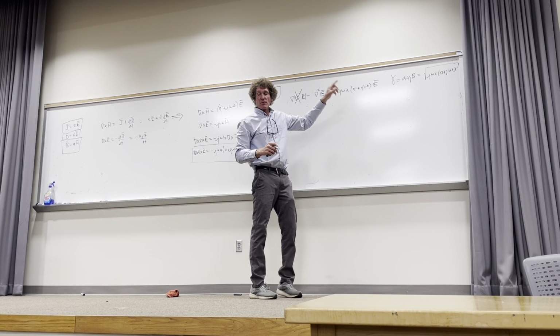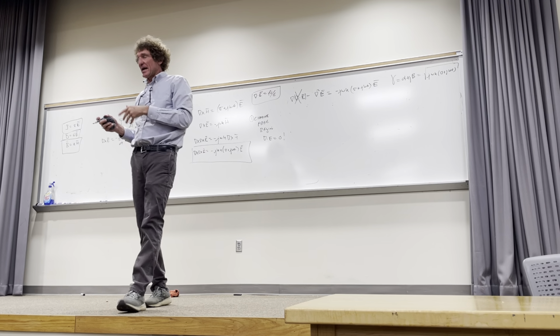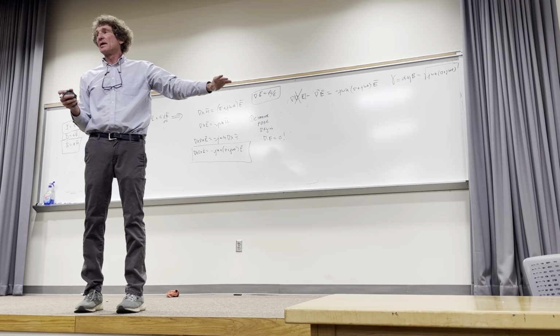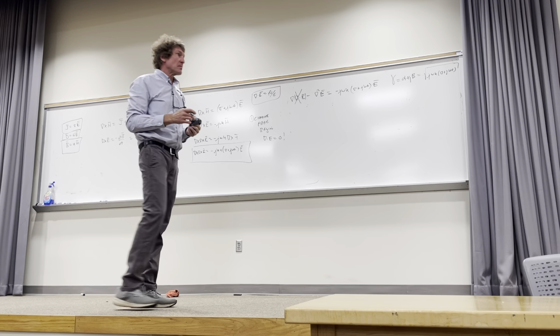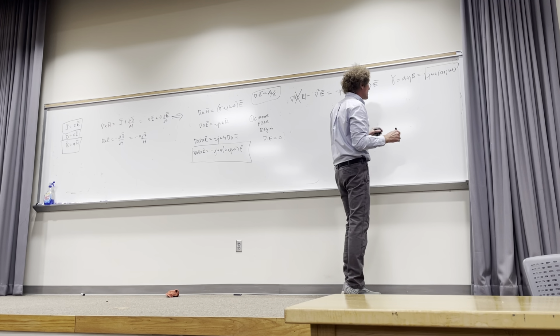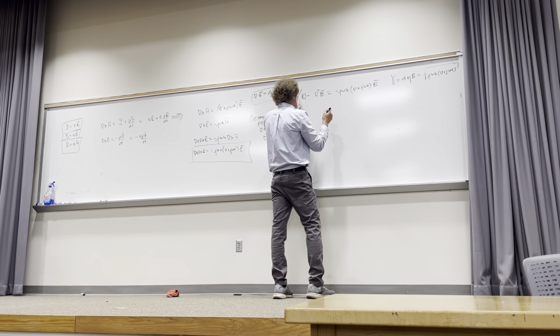Now you remember gamma when we did transmission lines back in the day, gamma had alpha plus j beta too. Alpha had to do with the attenuation, and beta had to do with the wave number. So this is gamma, and that's just the propagation constant. And I come over here, and now I can see I've got rid of that.